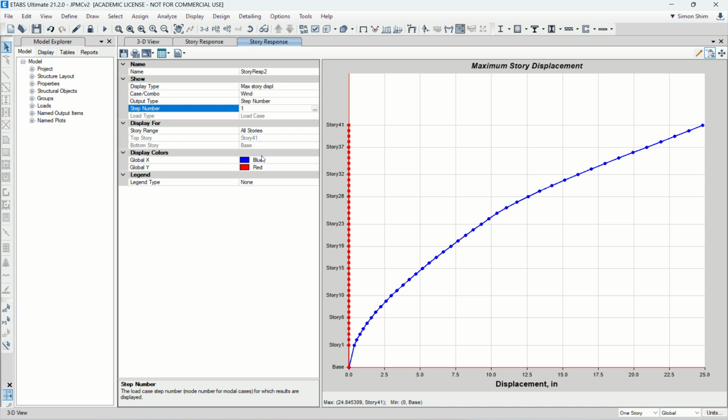We haven't sized anything yet, just using default, maybe 12 inches. Concrete strength, we haven't done anything. Just what I tried to show you is how to define and set up the wind load, right? And try to apply the wind loads, but in order to do that, you need to define these diaphragms. So ETABS registers the building width in X direction, Y direction, and the floor to floor height. Using width and height and wind pressure, it can calculate the total wind load at each floor, right?